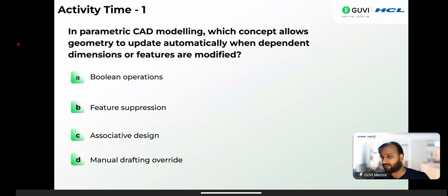When you start designing, for example, you just created one sketch, and in that you gave the length and breadth. When you are giving the dimension, the option will appear of whatever you have declared already, and then you need to select that option. Like for example, for length, you have already given that dimension. You can just select that. That will be its length.